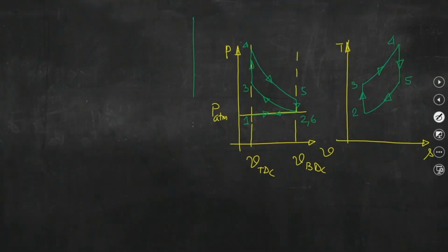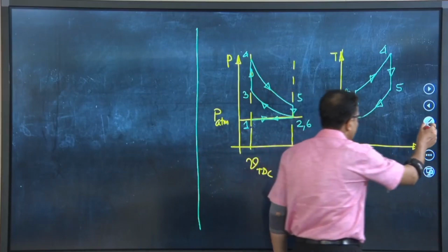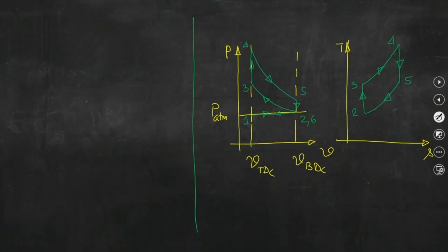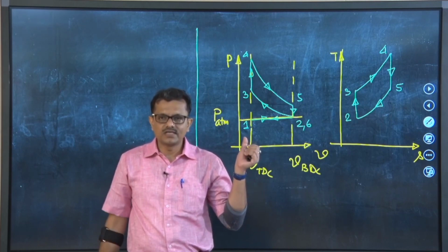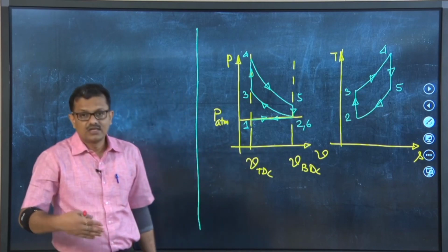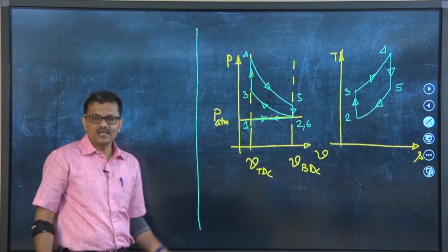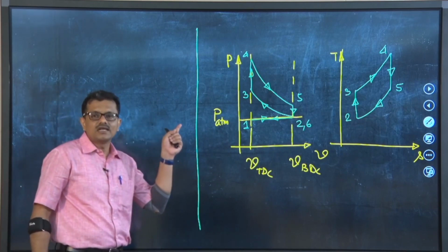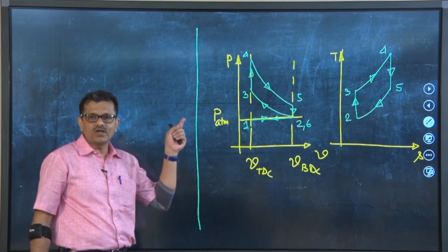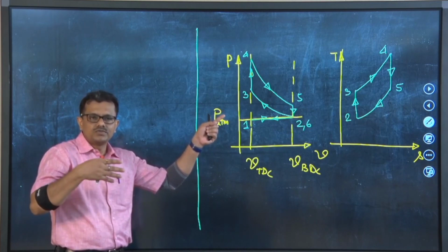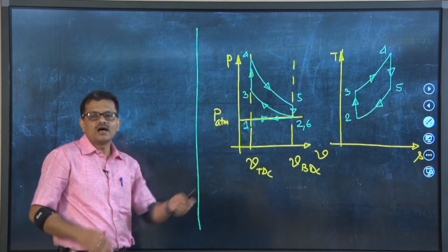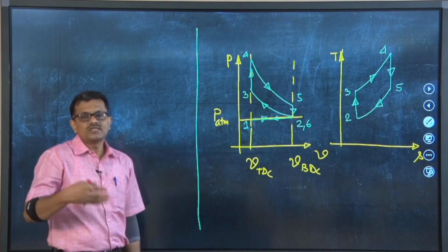Now, if we try to analyze the performance of the SI engine, let us discuss certain issues. What are those? We have discussed that to analyze the performance of the SI engine, these cycles, which have 4 different processes, are compared with an air standard cycle, and that cycle was first invented by Nicholas August Otto, and is known as the Otto cycle. So, we are trying to compare all the processes which together constitute the cycle of the SI engine, approximated with an air standard cycle.